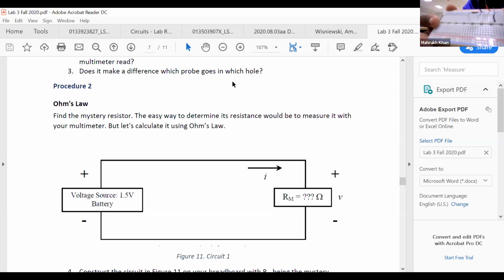So that's how I put the resistor. Okay. Now I need to connect the power. You are able to move the resistor legs like that and put it in the breadboard. You should always connect it in the horizontal direction, because these horizontal rows are not connected to each other. Okay, so we are done with that.